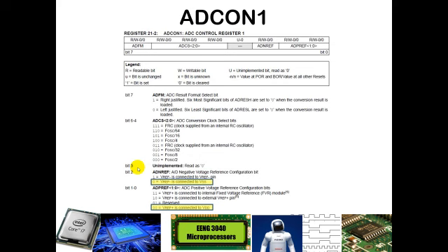Why would you ever want to choose something different? Well, if you know that a signal range is always within a certain window that may be not always going all the way up to 5 or all the way down to ground, you can choose to generate an external analog signal and have that be the boundary. But we are not going to do that this semester. I just want you to be aware that is a possibility.